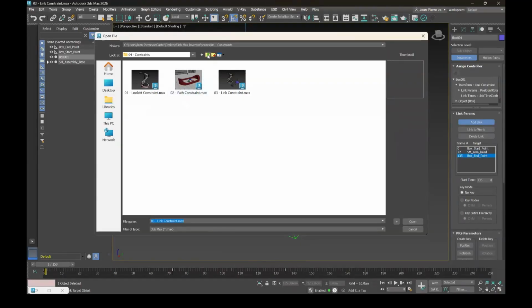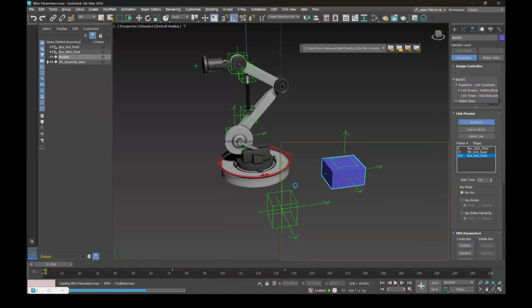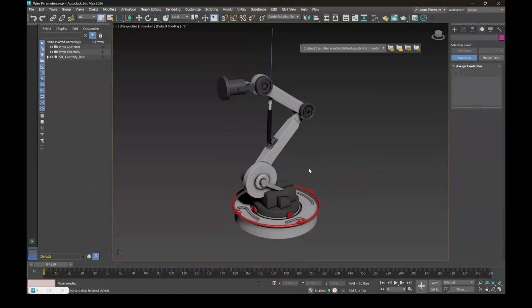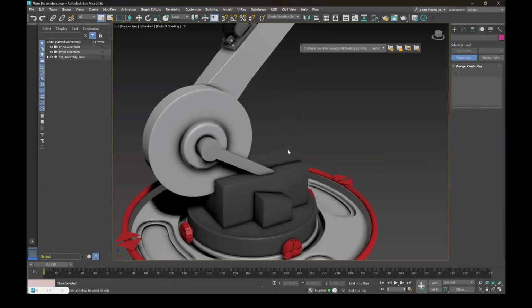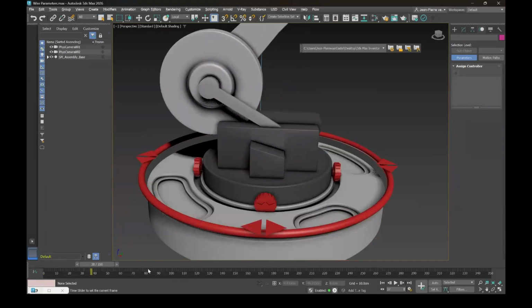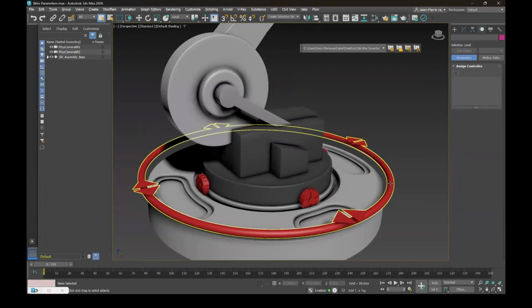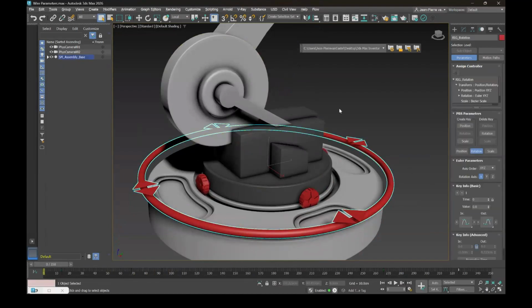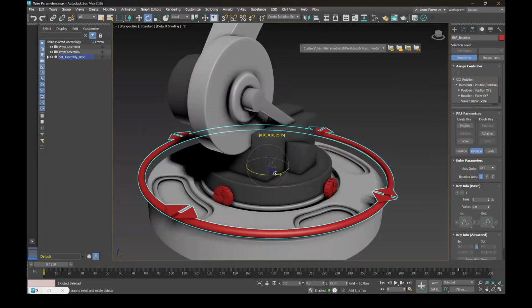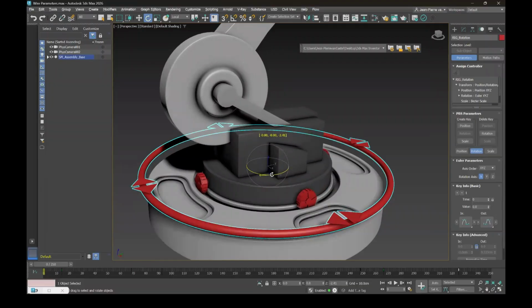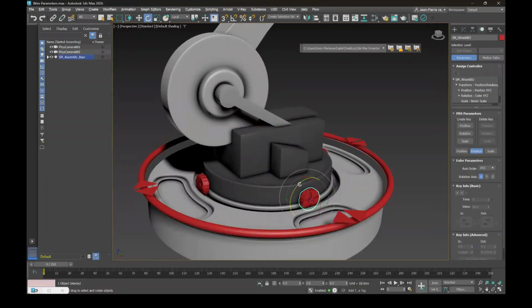Another one, which is also gonna be a time saver, it's wire parameters. So where I can create some mathematical expressions. Imagine this particular object is rotating, but the small wheels aren't. So I need to make a connection. When I start rotating this particular red object, which is the z-axis, this wheel needs to start rotating on the y-axis. That's what I'm gonna set up.